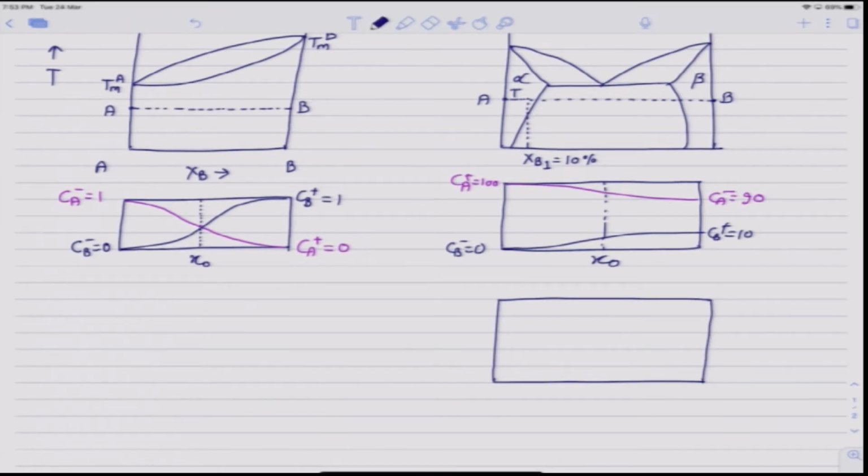So, obviously, in this case A and B both have different phases to start with. On the left terminal alloy I have phase alpha, right terminal alloy I have phase beta. So, there has to be an interface between alpha and beta. Let us denote this interface here as xi. Now, it has to be noted this xi, the interface position, is not necessarily same as the Matano plane position x naught. We will talk about this in the next class, how to determine x naught for this, but just remember now that xi is not same as x naught. Xi is the interface position, that is where the alpha transits to beta within the diffusion zone.